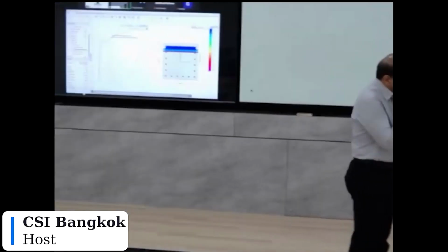So there will be some difference between the fiber mesh that some programs use and the exact integration that we are using here. I think a lot of the information we presented is quite helpful in evaluating the column's capacity as well as curvature. And most importantly, the understanding of the stress strain state for a given loading.